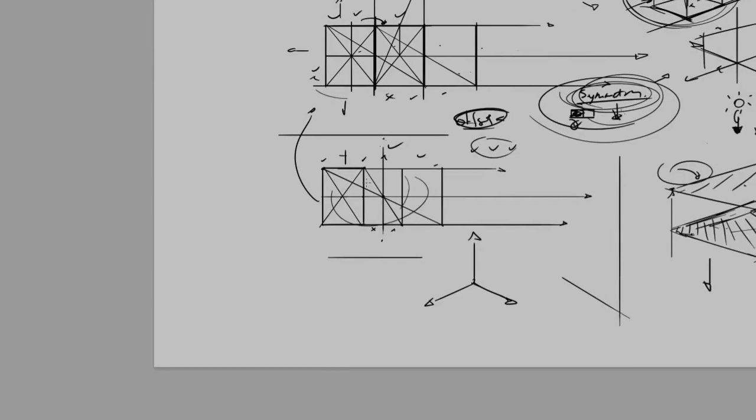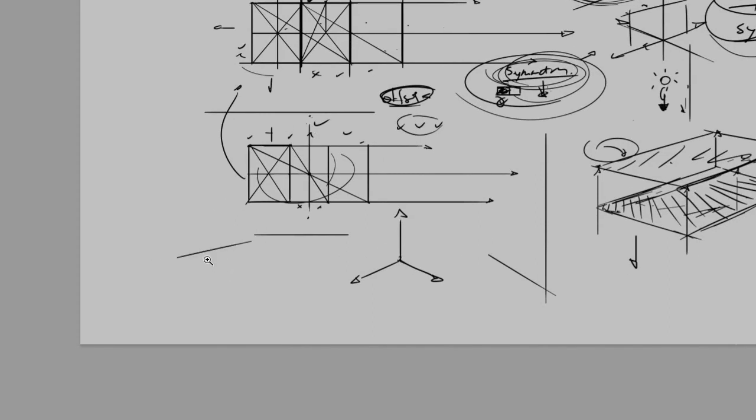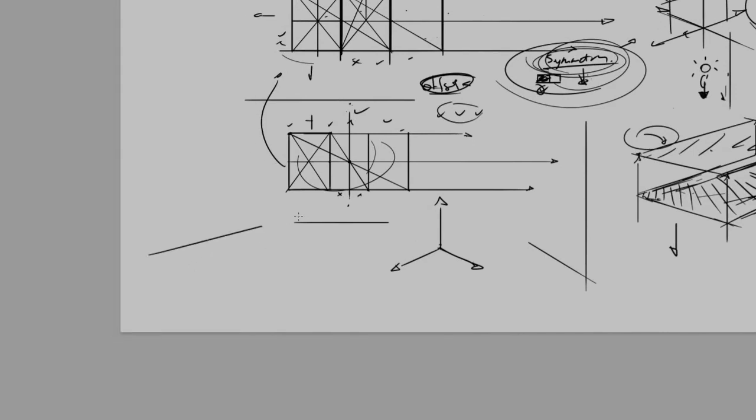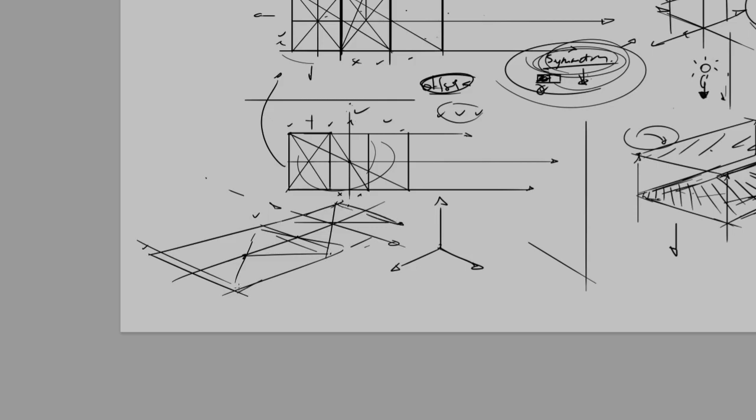But it's easy to go from here and put this whole thing in perspective as well. So if you have a plane now, alright, now you've got this flat plane, and you want to mirror it to that side, so you just want a little bit distance in between, but you want the same dimension. So your mirror line actually follows the rule of the perspective grid, going to the left vanishing point, going to the right, as with these, and then you just do the construction. So the important part is to find center there. So I'm using this rectangle, find center point, alright, and then the only difference is I have to take these two edges across this line. So edge 1 is going to be somewhere there, and edge 2 something way back there. Alright, okay. So 1, 2, go.